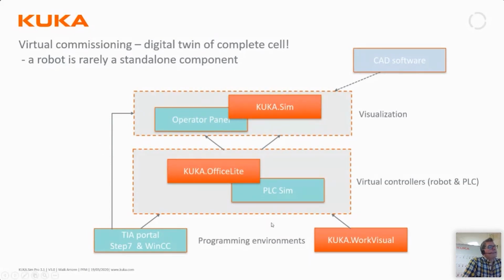What we then could do, but seldom did in the proper way, was to download the pre-designed code into virtual controllers. That is PLC.Sim. We used PLC.Sim somewhat, but that was rarely on a standalone basis, not connecting it with a cell layout in total.